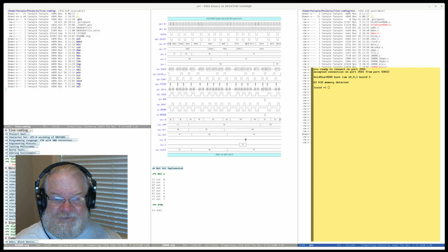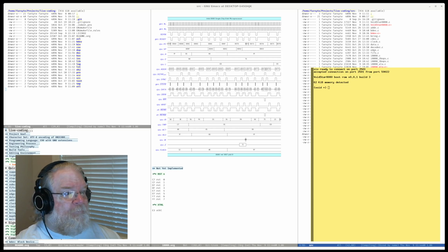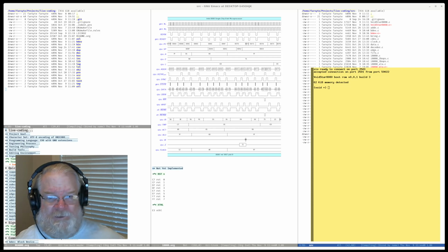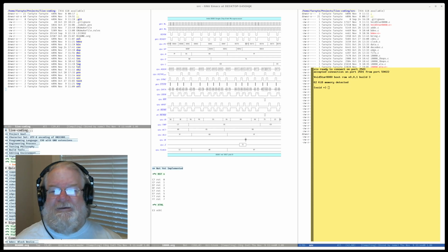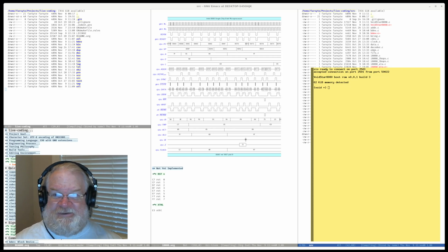because inside Forth, what have you got? Well, I can read blocks of memory and write blocks of memory and peek and poke at things, which is what you want to do when you're bringing up a new computer. So instead of writing a monitor ROM to do all these things, I thought, well, I'll just grab my copy of FigForth and make the small changes to it necessary to get it to talk to the simulation. So for instance, FigForth wants to call the CPM BIOS to read and write characters and to do disk reads and writes. I just rewrote that little bit of assembly code to do the inputs and outputs to get it to talk to the simulation, and Bob's your uncle.